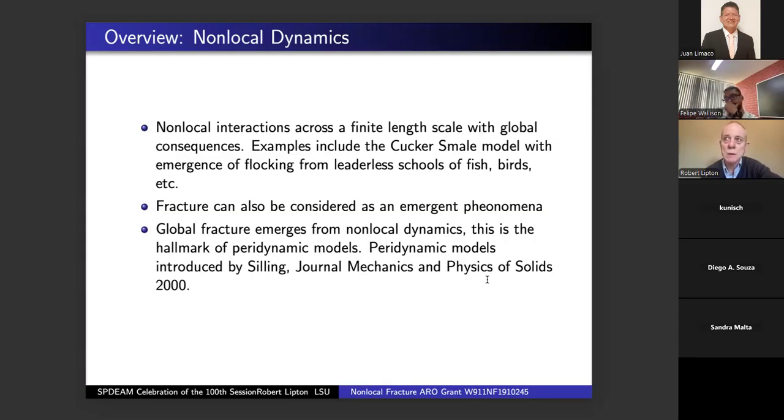So these non-local potential energies at the atomistic level through gamma convergence can be recovered at the macro scale as Griffith fracture energies. The Griffith fracture energy was introduced back in the 20s and now is a staple of the modern theory of fracture mechanics. And so very interesting connections are being made here. So I'm going to continue trying to make some new connections.